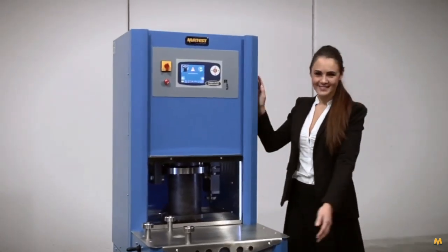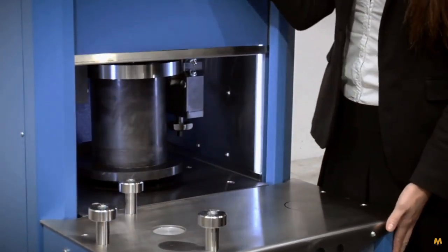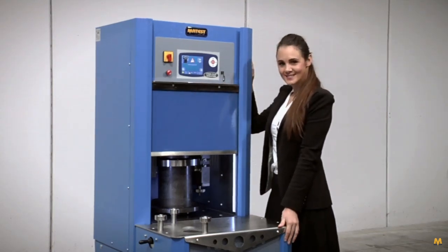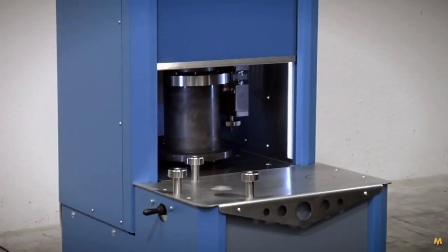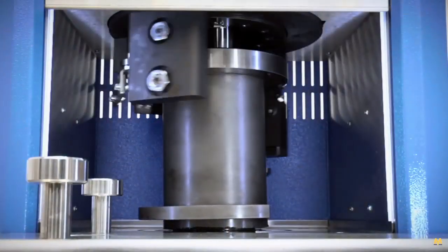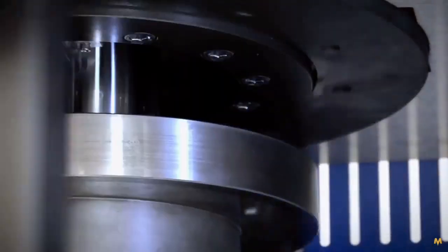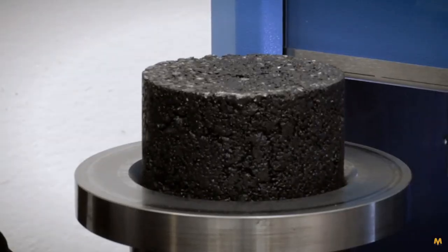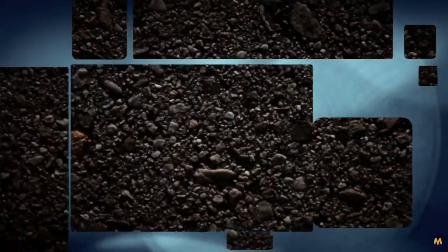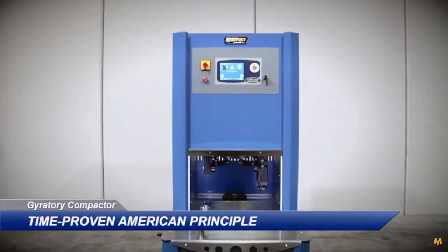NIHTE Gyratory Compactor is designed and manufactured with the latest technologies in accordance with the SuperPave system and complies with ASTM, AASHTO and EN standards. It has been developed for the SuperPave asphalt mixture design to avoid premature deterioration of asphalt pavements. The machine is used to simulate the real compaction conditions under actual road paving operations to determine the density and compactability of hot mix asphalt and to prepare cylindrical specimens for Marshall and AMPT tests. It is developed following the time-proven principle used on the original Texas DOT gyratory compactor.